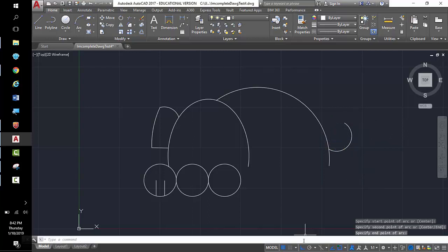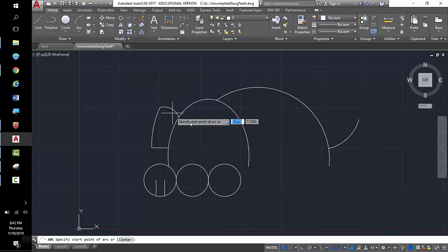That's not working because I have ortho mode on. In order for this to work, I need to turn off ortho mode. So I'll delete this, turn off ortho mode. Let's try again. I'm going to snap to my object and then draw a long, slightly curvy object. Now I need another slightly curvy object attached to that, and I need to snap to it at the end.